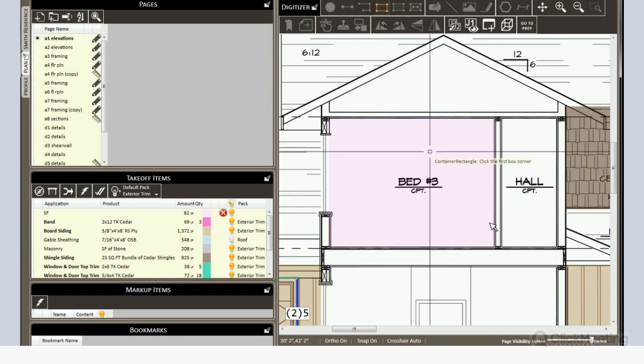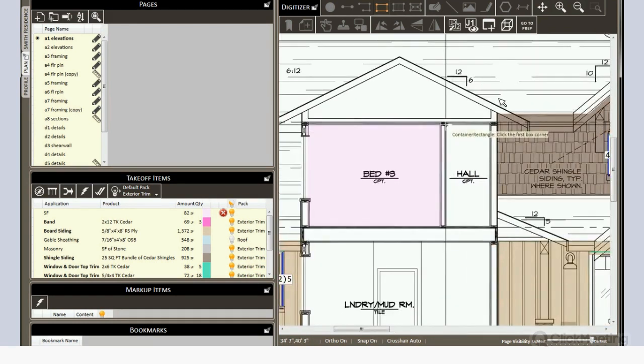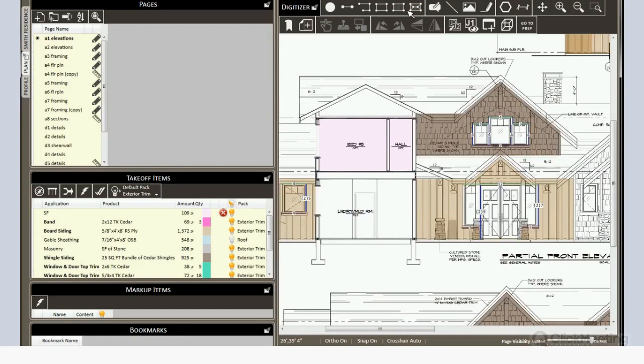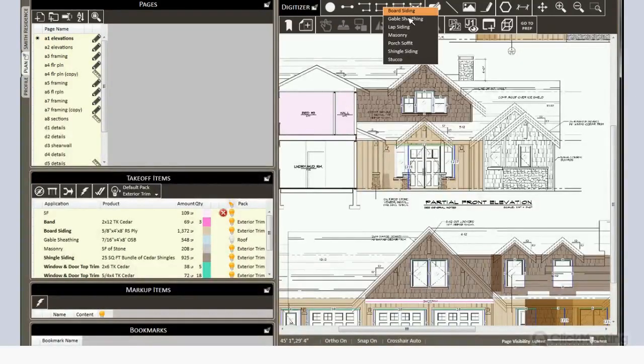And I can continue to draw those as we go. So similar to the box subtract section feature that we already had previously, but now you can make use of that for drawing actual areas. And the same would also be true for floor containers and roof containers as well. And the same is also true for presets. So if you come to a preset and again hold down Shift when you make that selection, then you can go forward and draw with the area.